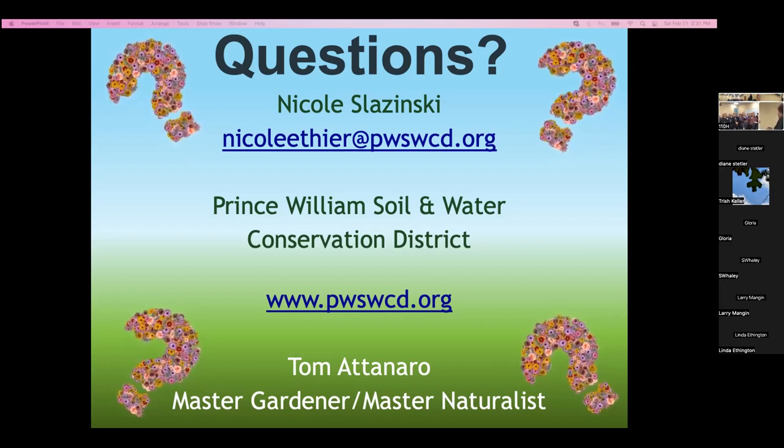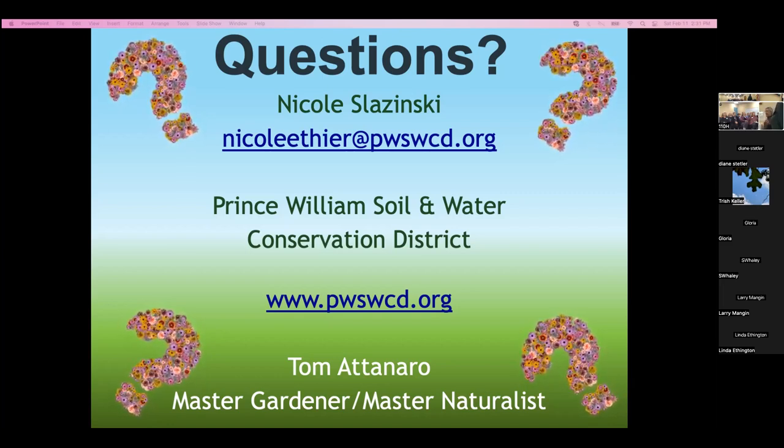One of the things that sometimes is counterintuitive about a rain garden is the bowl will actually be drier than the rest of your garden sometimes, because you're actually putting in good drainage. If you live in Prince William County, which has a lot of clay, and you have a lot of leaf cover, the supposedly wet part of your garden may be drier than the rest of your garden, because the rest of the garden with that clay still retains the water, unless it's in full sun and dries up completely, but in shaded environments it stays moist.